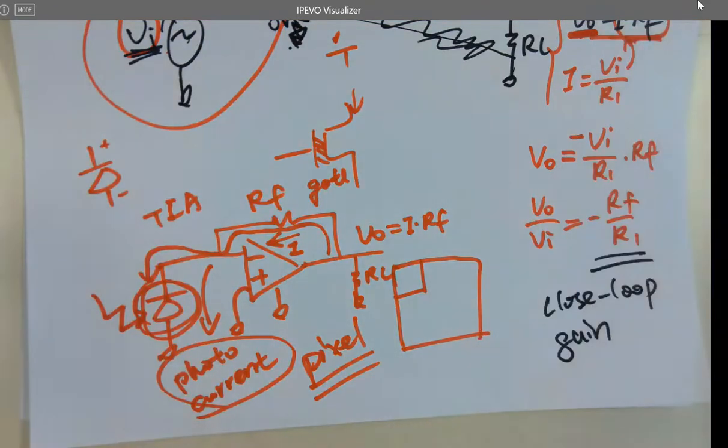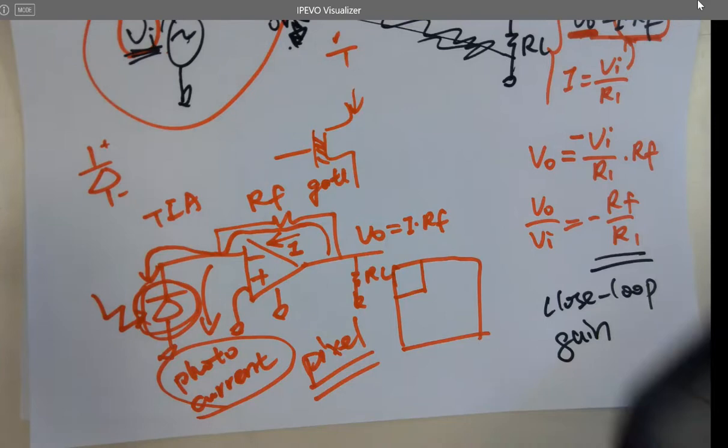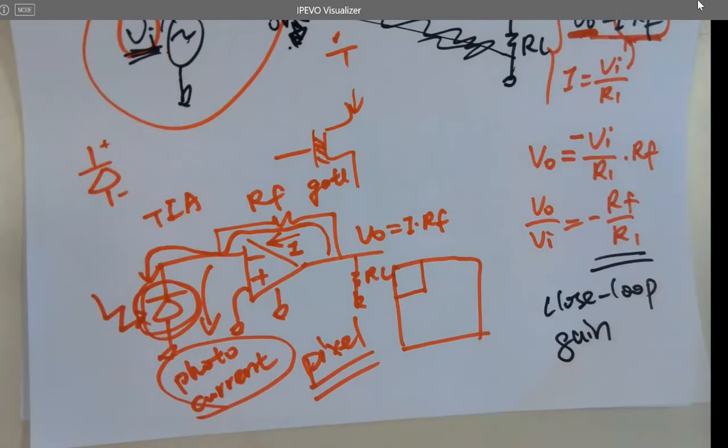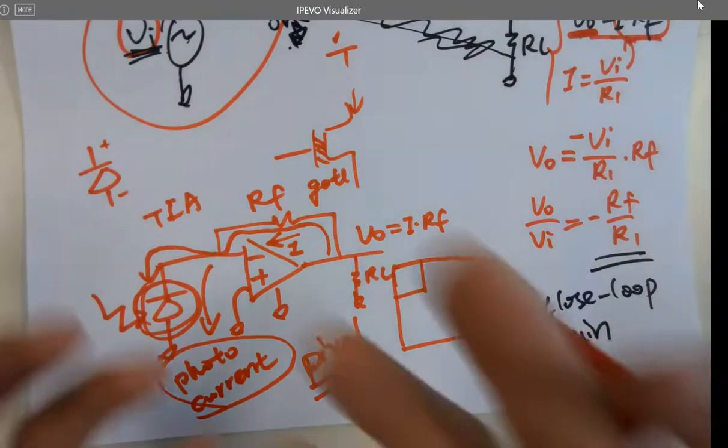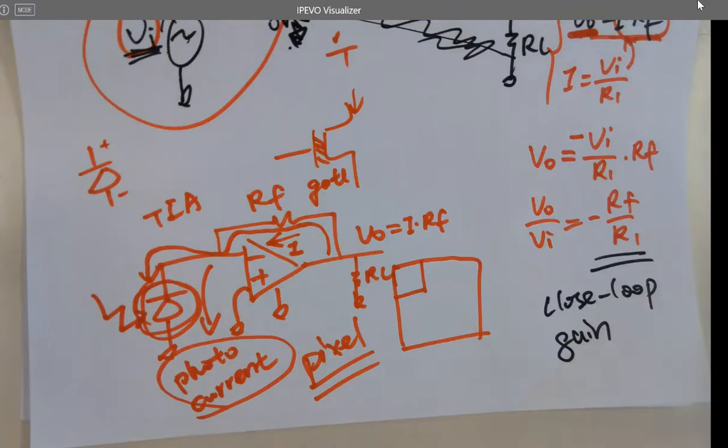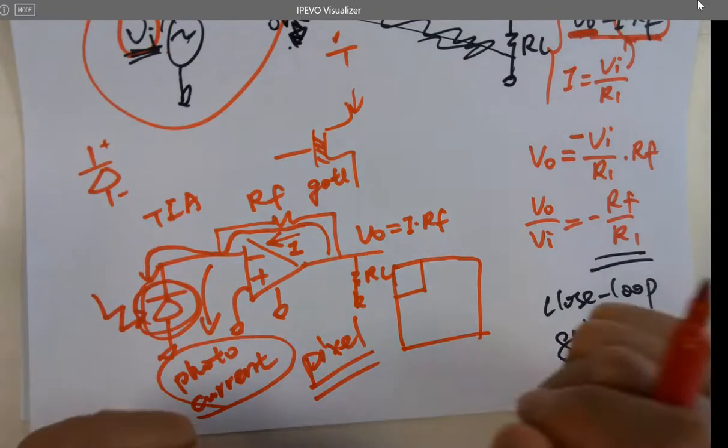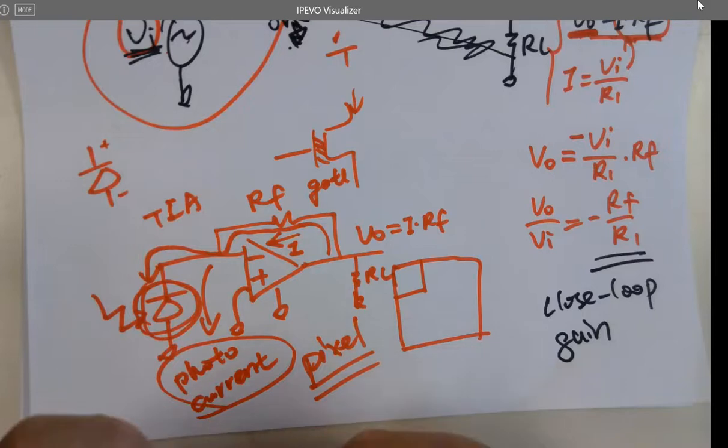And then it goes to the ADC, analog to digital converter, which converts that analog voltage into 8-bit, 10-bit, 12-bit digital signal, right? And then sends it to the CPU bit by bit. It stores it, processes it and sends it to the display module so you can see something, right? And while I was talking about that, it's already streamed millions of pixels. That's how that works. It's everywhere.